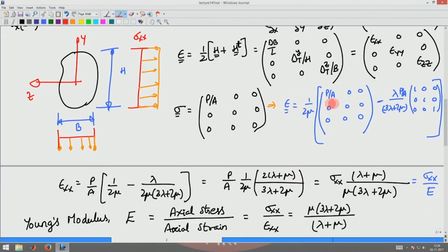Now this is basically relating the axial stress to the axial strain. Okay. So let us go back to the equation we had before, which connects epsilon xx, which will tell what epsilon yy and epsilon zz are in terms of the applied stress sigma xx. You will find that both are the same expression, epsilon yy equal to epsilon zz, which is given by the same expression, which is this term alone. Okay. So let us go ahead and do that.